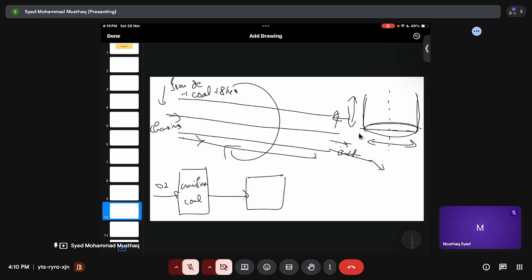followed by the gas heater. That means, as I have said before, you need to preheat. If you don't preheat, the reaction temperature, the active reaction zone temperature, will go down. Then you feed it to the Midrex process, because as I have said before, Midrex is for the shaft furnace. Shaft furnace means the vertical tube. Here it is, the vertical one.